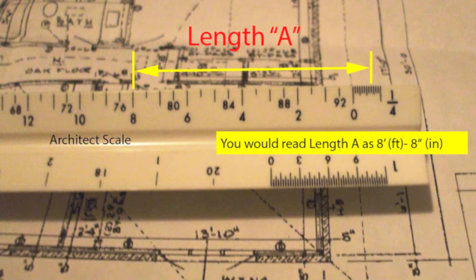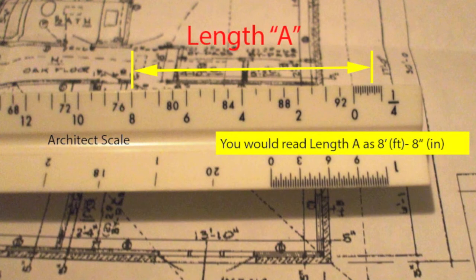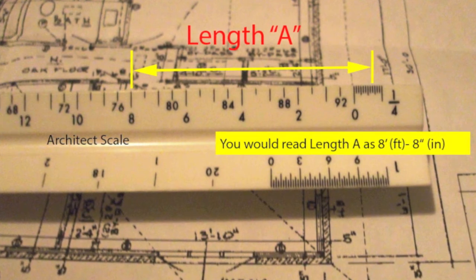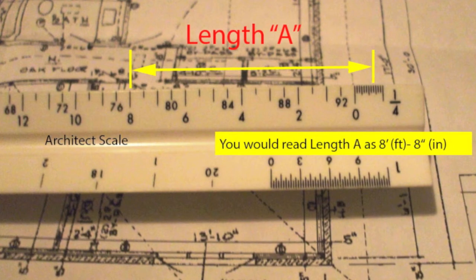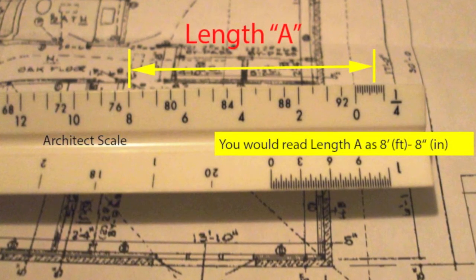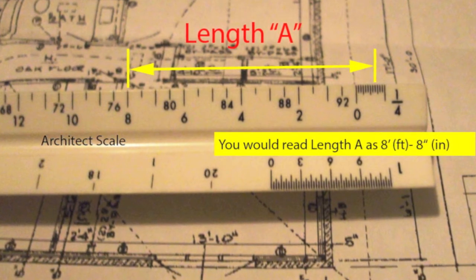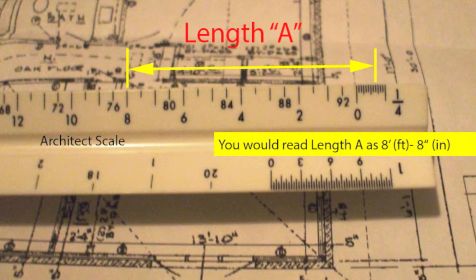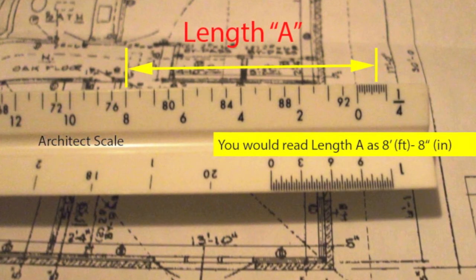Note length A in this image. Also note that we are using the quarter-inch side of the scale. Length A starts on the number 8. Each graduation on the elongated portion of the scale represents 6 inches. Read from 0 to the left as 6 inches, 1 foot, 1 foot 6 inches, and so forth to 8 feet in length.